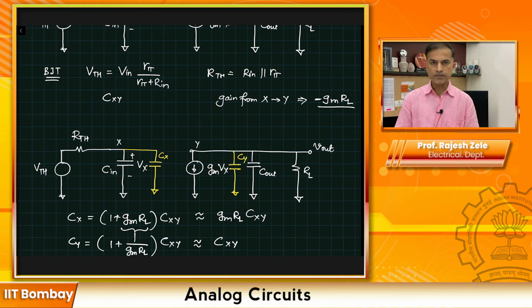If this looks new to you, then please look at the Miller effect and how we split the gap between node X and Y: whenever we have a gain from node X to node Y and a capacitance between those 2 points, we can move that capacitor from node X to ground and node Y to ground using the Miller effect. And that's what this is all about.